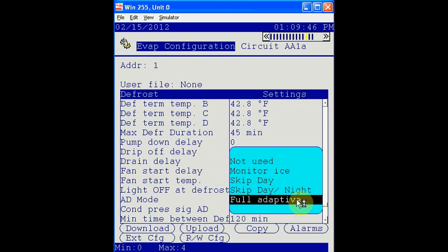For this mode to be utilized, 4 things must exist on the 750. The coil outlet sensor, the return air sensor, discharge air sensor, and an AKV valve must be used. The AKV valve is used as a flow meter. The coil outlet and return and discharge air sensors are used to create calculations that determine if there's ice buildup on the coil or not.